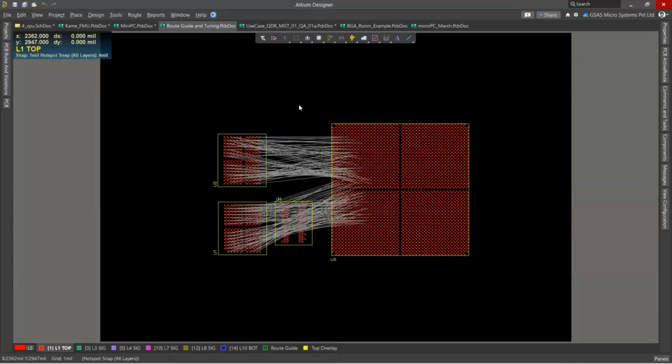In active route, we have the flexibility to route a group of signals, I mean a net class, which will help you get the finest result. The user has control over which net is routed on which layer, and you can also define the path for the routing. Whereas in the auto router, we can't define the path or pick the nets.